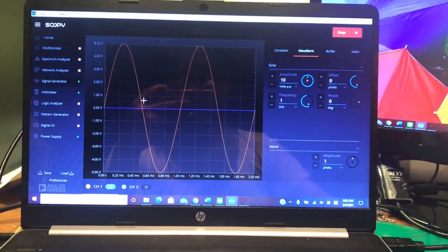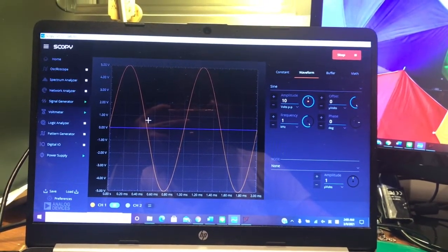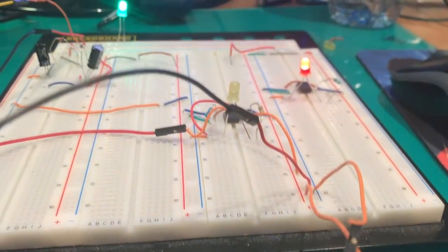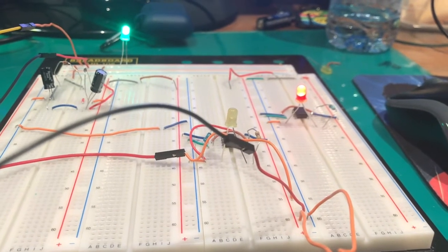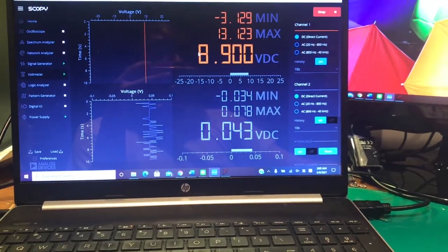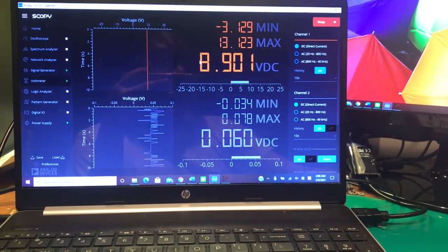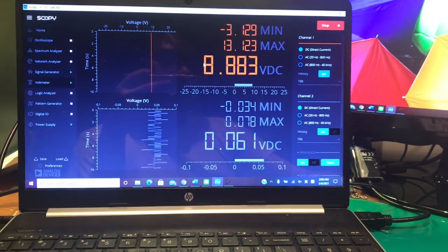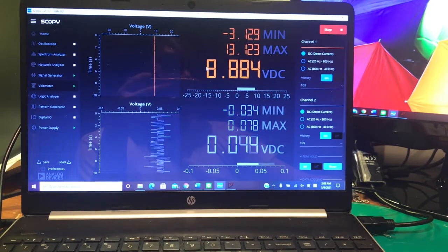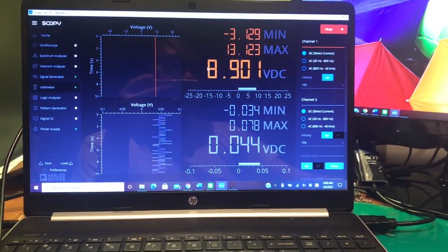Then if I use a signal generator to generate a 10 volts peak to peak 1k hertz signal, as you can see, the green light represents that it is receiving the data. Now let's see the output for the voltage doubler. Although I'm still in the process of debugging this, I'm able to generate the DC from the AC signal with no other issue. So after supplying the signal, I was able to get around 8.9 VDC, and that would be our power on voltage for the current sensor.